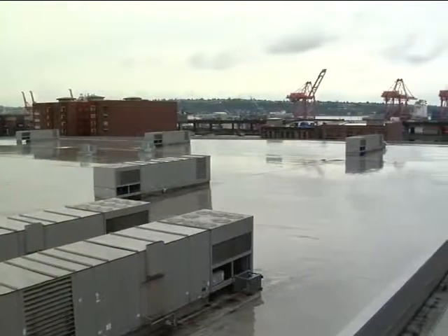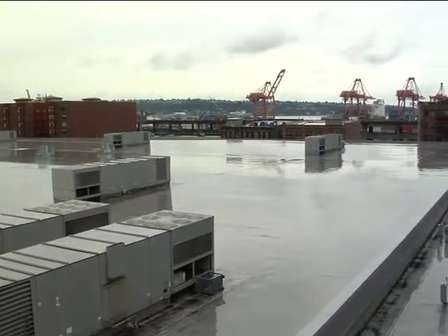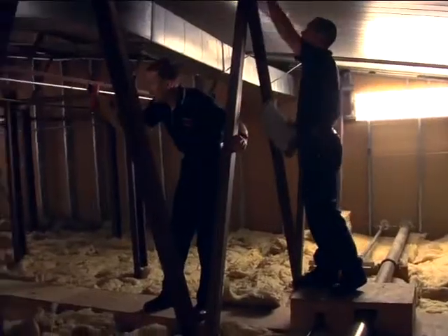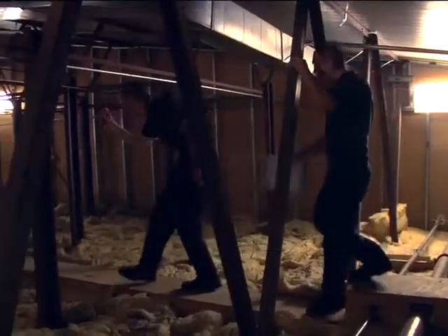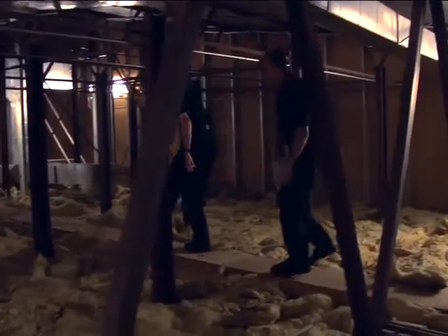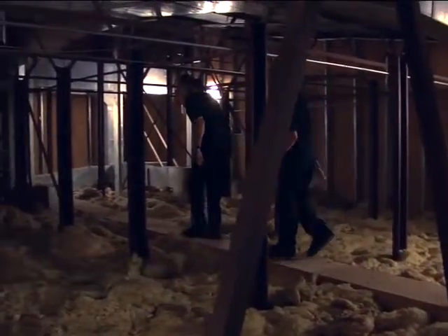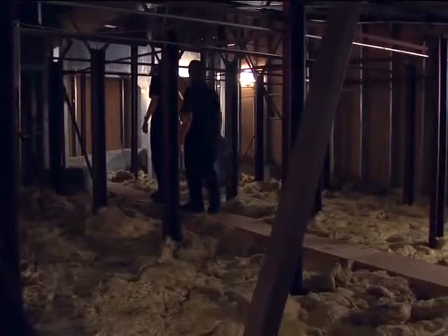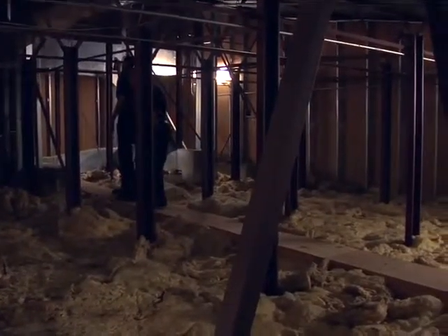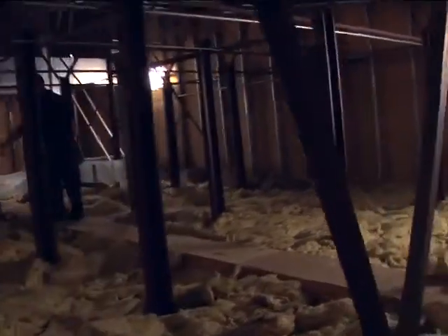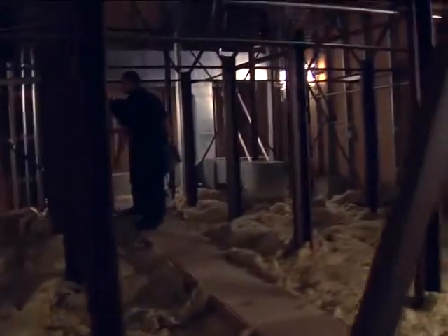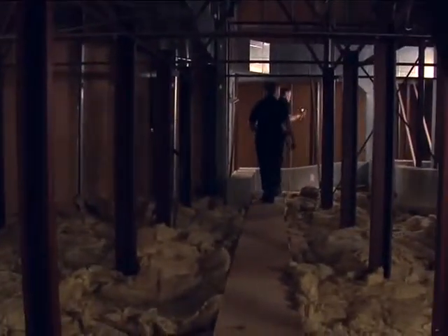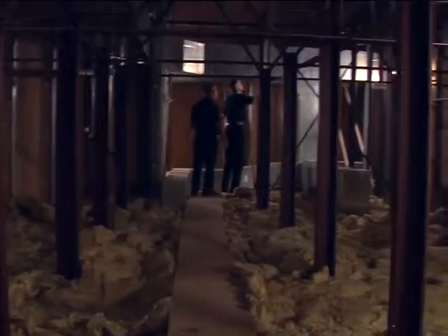Some flat roofs do not have joists, but instead are made from concrete or precast gypsum. It's important to be aware that flat roofs often have a cockloft. A cockloft is an open space between the ceiling of the top floor and the roof. Flames can travel very rapidly from one end of the structure to another once they reach the cockloft. Fires in these spaces can rapidly weaken the roof.